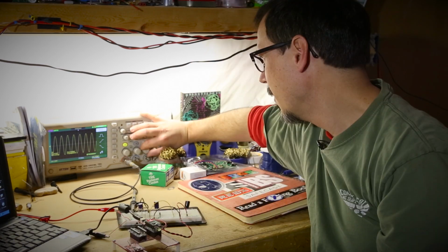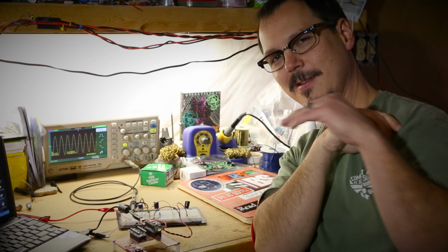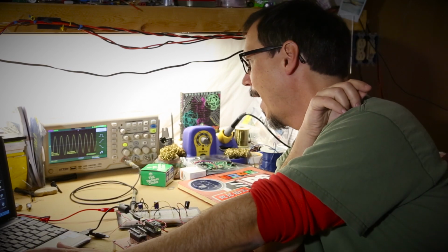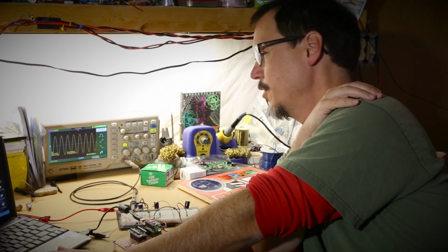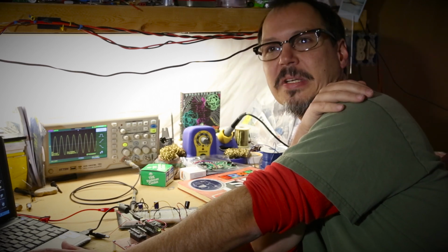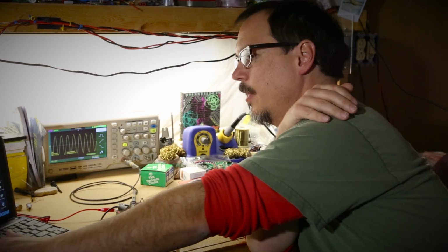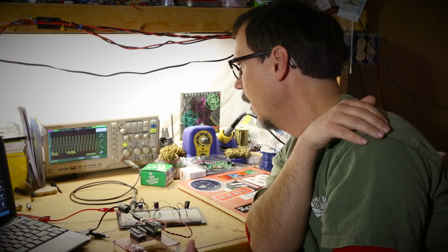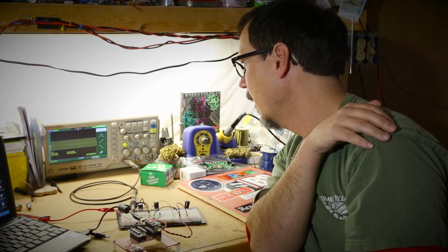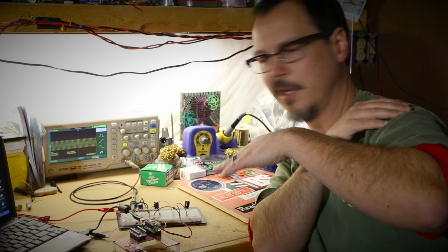Now let's crank it up. So at 100 kilohertz, I'm still at 10.8 volts. It's less than the max, but starting to taper off a bit. For the cutoff frequency, we're talking about half. You define that by half the voltage, okay? So if I'm at 11.3 peak to peak, I want to be about 5.65, and that's about the bandwidth. So it's a little more than 100 kilohertz. Let's try 200. 9.2, let's try 500 kilohertz. And now we're at about 5.2 volts, so it's a little less than 500 kilohertz is the high frequency cutoff.